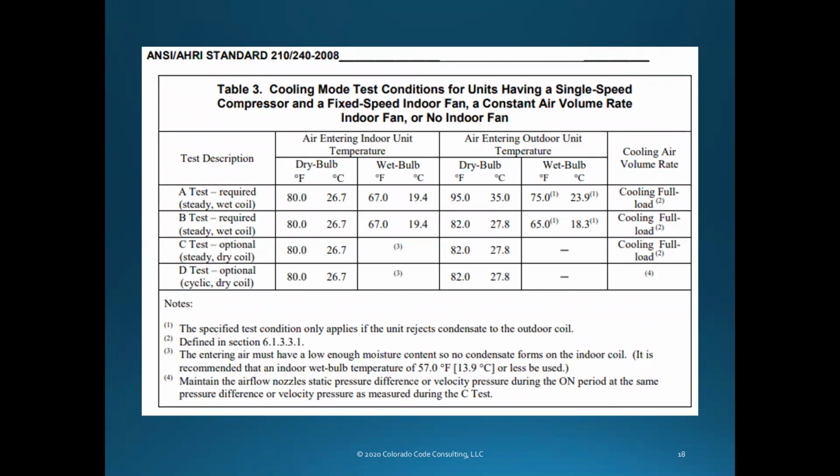Yeah, well, it doesn't have the same capacity at 115 degrees outside because guess what? It can't cool off as much, can it? You've got 115 degree air moving through it rather than 90 or 95. So that's why it's important to have those expanded performance tables. And it's important that the mechanical designer knows because the software has no clue. It only knows AHRI. That's what's in the databases and that's what the software has, and they're not correct. I mean, they're correct as far as AHRI is concerned, but they're not correct for what we're designing to.